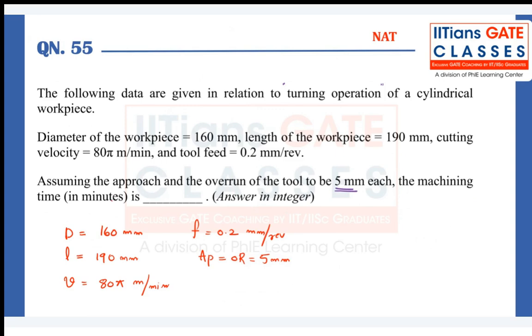Now, what we need to find? Machining time calculation. Here we have a formula: machining time is equal to L divided by F dot N. L divided by F dot N. Clear, everybody, guys? Hope you understand.